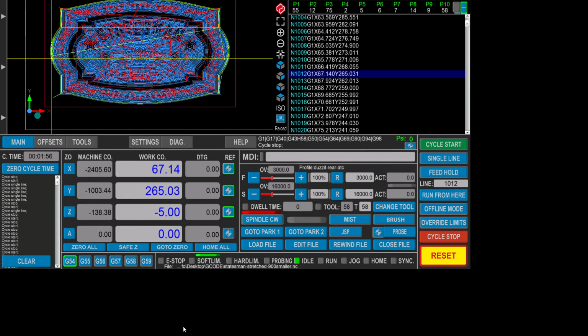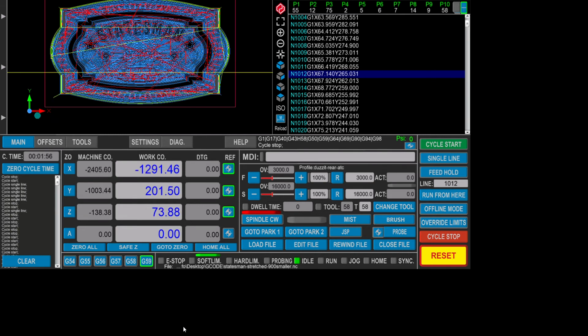So just for instance, on my machine that I use daily, I have G59 set as a vice, which allows me to go straight to the vice, put a piece of work in, it's already set up, and I can just press the cycle start button, away I go. It's a fixed position vice with fixed stops, so as soon as I've pushed the work up to it and clamped up, it's in exactly the right position, and the machine remembers this all the time.